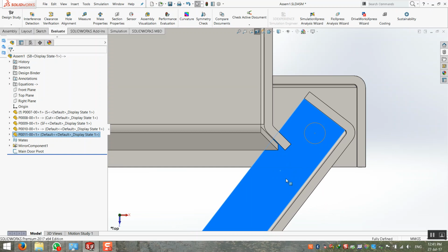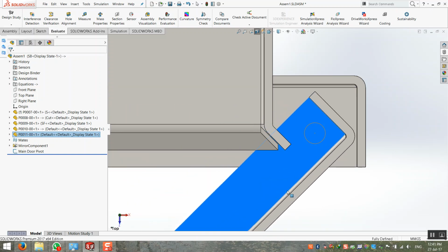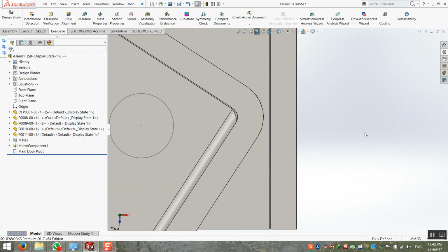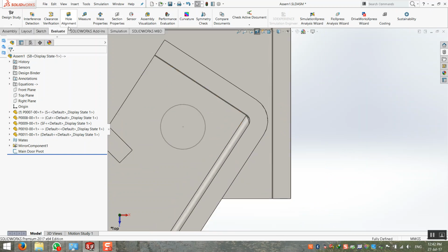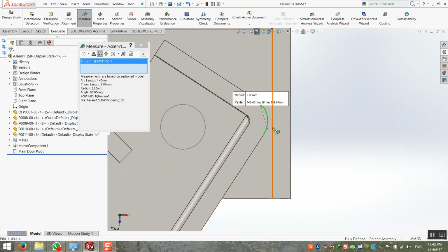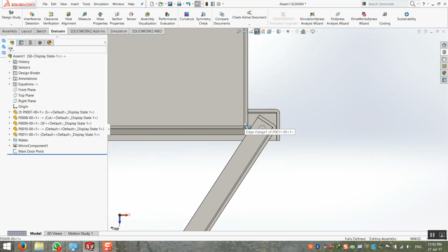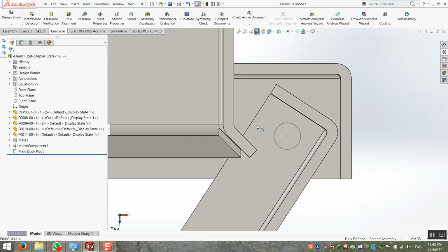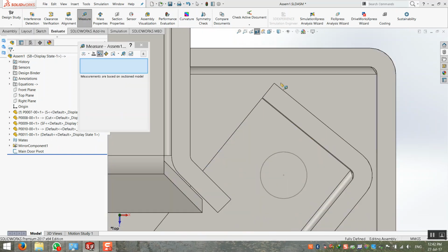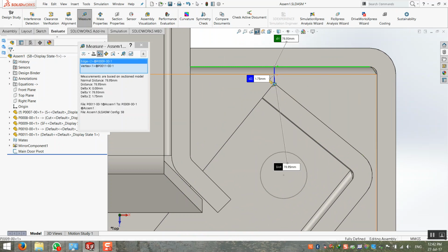Okay. All right. We can only check this dimension, because this is the minimum one. 0.5. 0.5 maybe after painting. After painting, the paint will make the sheet metal thicker. Okay. Maybe after painting there will be friction between them. So we need to avoid this one. From this way, I haven't a problem, because I found that we may have 1.7, which is very good.